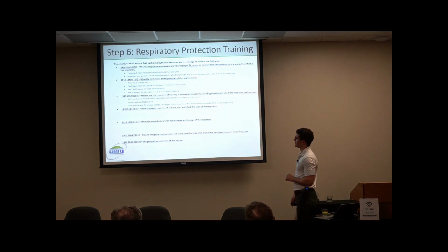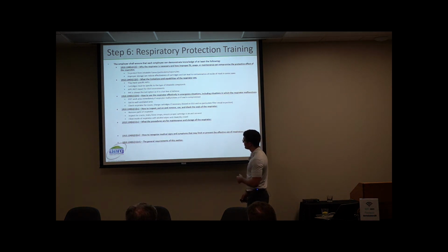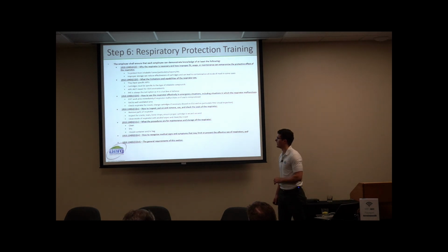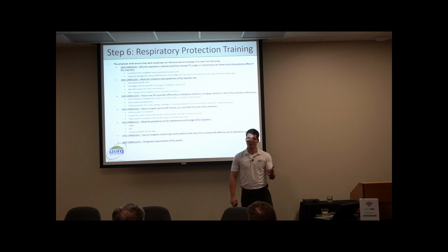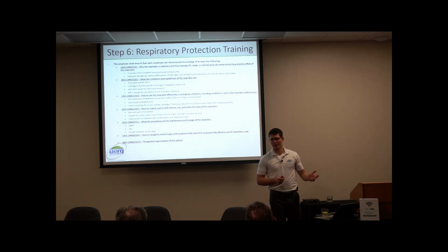How to use the respirator effectively, how to inspect, don and doff that respirator, and what the procedures are for maintenance and storage. This is a pretty common deficiency. I'm sure you know this one with dust masks or actual half or full facepieces. We often see these just left out on the table, right?